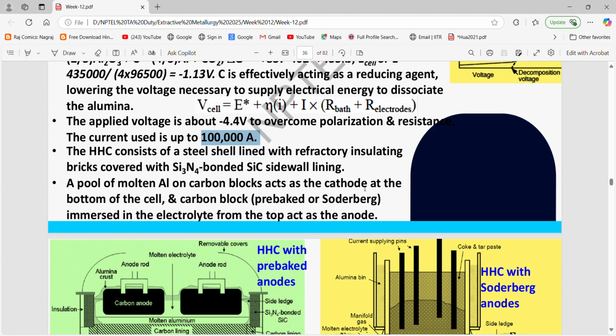That's why scientists generally say the recycling of aluminium can be 95% cheaper as compared to the raw aluminium production by the Hall Héroult process, because the Hall Héroult process requires a very high amount of current during the electrode deposition, molten salt electrolysis deposition of the aluminium, while recycling of aluminium can be done at a much lower temperature with the help of the electric arc furnace, or we can go with the normal reverberatory or induction furnaces.